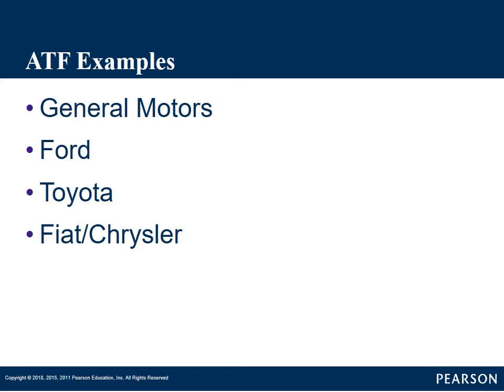Ford, remember we talked about Type F. That was used early on, but then for Ford it was Mercon. The Mercon is what they used for many, many years. And matter of fact, a lot of times you would buy a Dextron Mercon fluid. It was kind of a universal fluid that you could put in Ford or GM vehicles. A lot of times you probably go to Walmart today and get a Dextron Mercon transmission fluid.